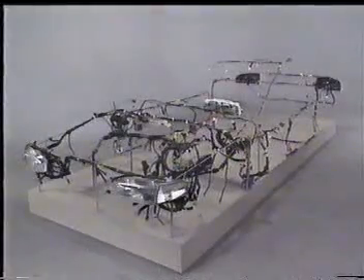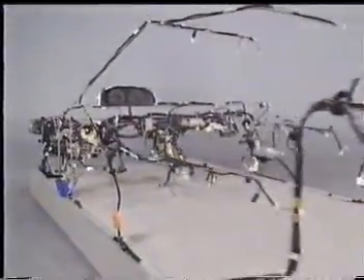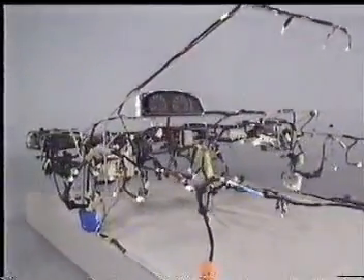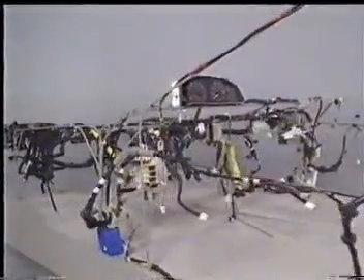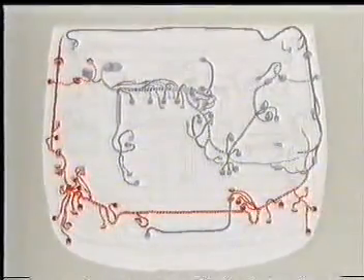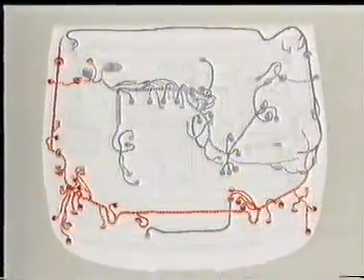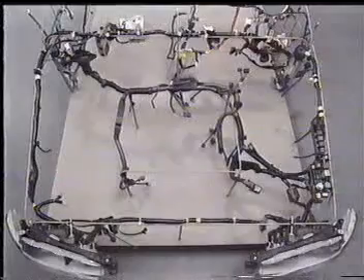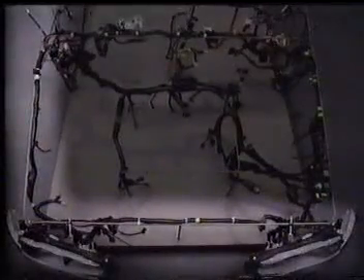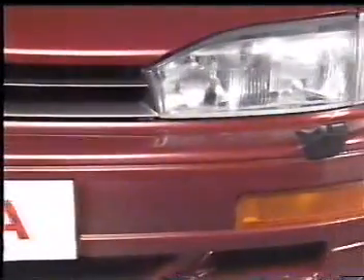Here are all the wire harnesses used in a single vehicle. Let's look now at the individual harnesses. First of all, looking from the front of the car, there is the engine room main wire harness. This wire harness is connected to the headlights, clearance lights, and turn signals, among others.